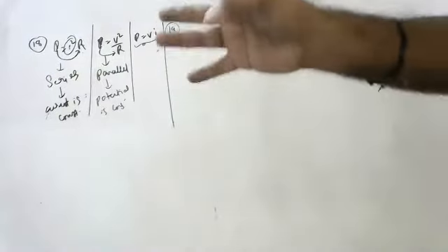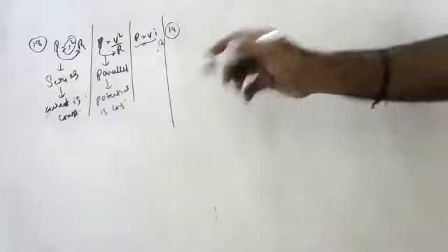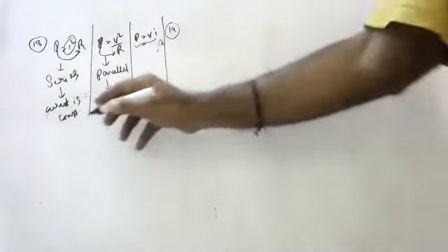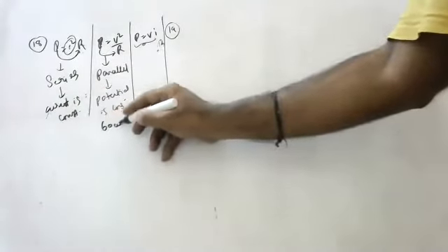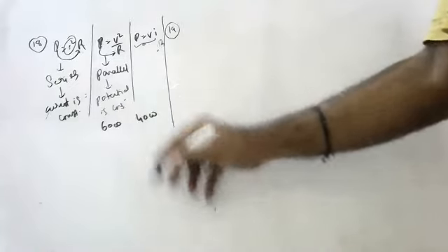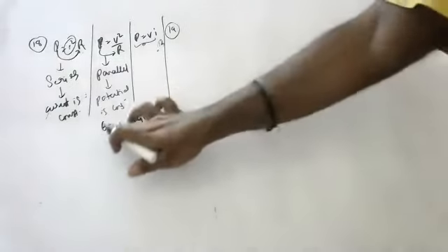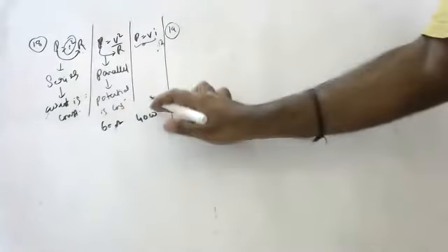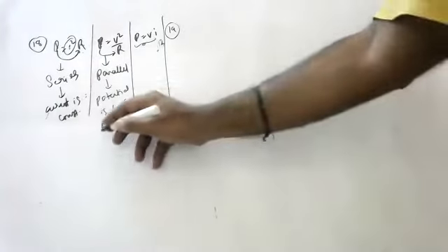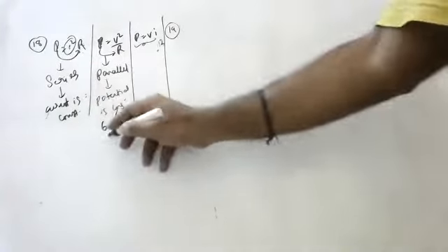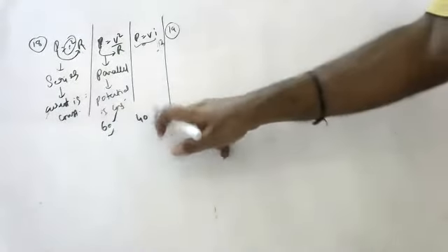So in series, power is directly proportional to resistance. Remember this. Based on this, sometimes they ask questions like this also, children. A 60 watt bulb and a 40 watt bulb are connected in series. Which will glow more? Because this one has more resistance, it will have more power, so it glows more. If watt is given directly, you can say the 60 watt bulb.